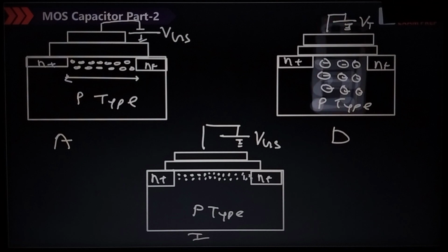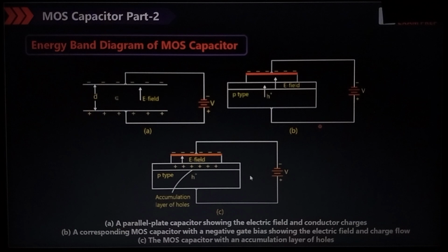Now I am going to change the orientation of this highlighted portion. So this is the metal, then SiO2 layer, and then what? Semiconductor. The width of the semiconductor is high as compared to what? SiO2 layer. So when I am in a vertical direction, this is the thickness of the SiO2 layer, TOX. Okay. Now try to understand. First of all, tell me when I am applying the negative voltage between them, during accumulation, what will be the direction of the electric field? Watch this diagram.